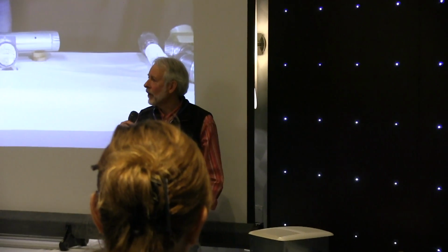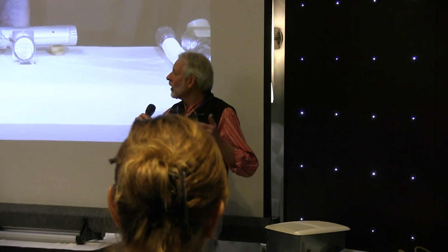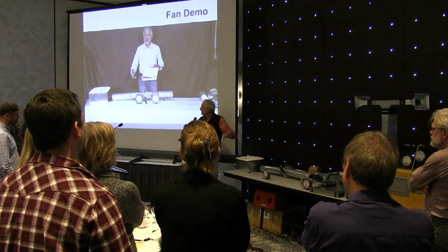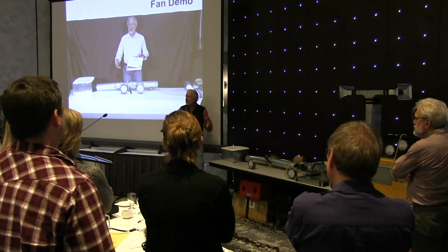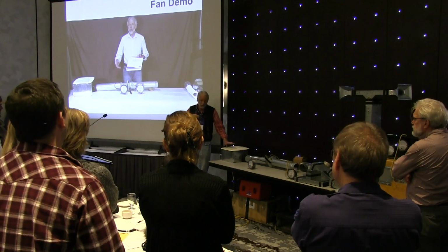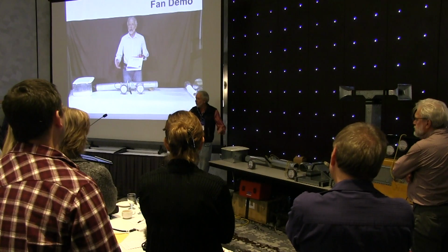Does anyone want to hazard a guess why when it's blocked it uses less power? It's not doing any work. It's not moving air from point A to point B, so it's actually just windmilling like a stupid chipmunk. So there's no power consumption. The fan's happy. This is not a smart fan. This is not a compensating fan. It's a PSC or shaded pole motor.